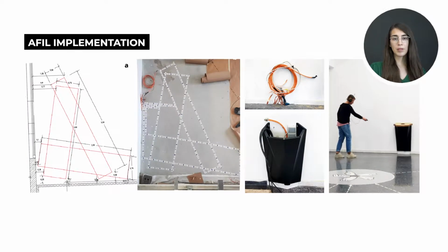For the on-site implementation, we drew the final topology on the building plan. The electrician of the school laid the flat copper tapes before the final layer of the floor was placed on top. All active components were placed in a custom-built metal enclosure. We performed further tests using a receiver to make sure everything worked as intended.